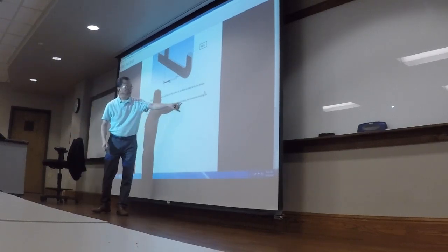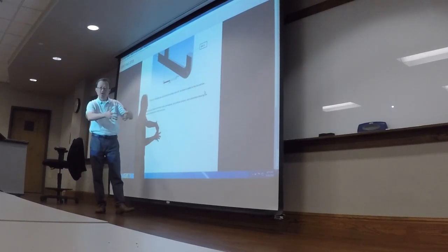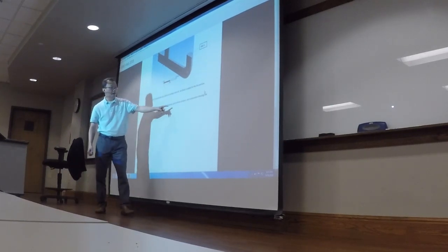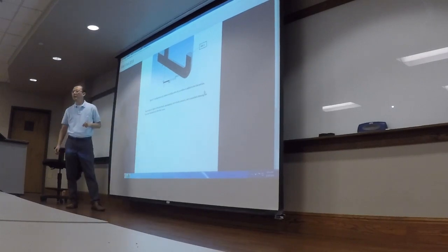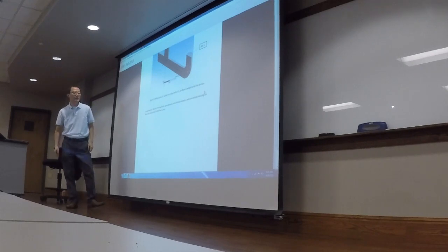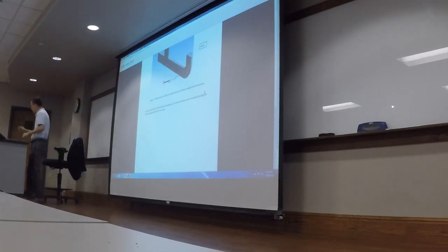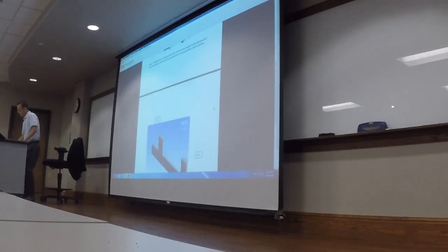Then velocity contour, and the screenshot showing the flow rate distribution, for example 95% will go through the line portion, 5% will go through the branch portion. I would like to see your screenshot, not your handwritten numbers, so I know it is a result generated by this software. Right? Okay, so let's do it step by step.